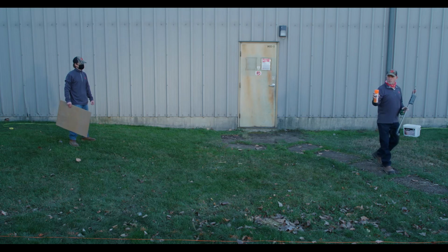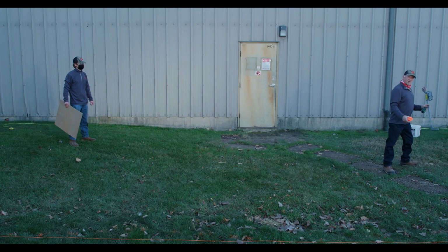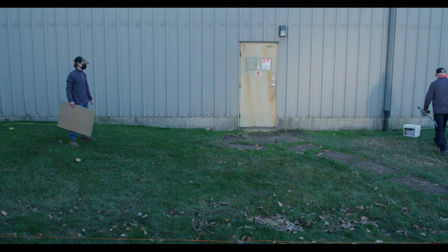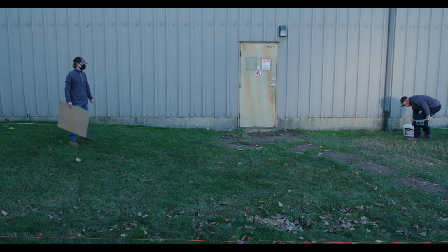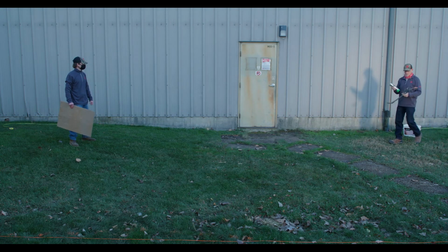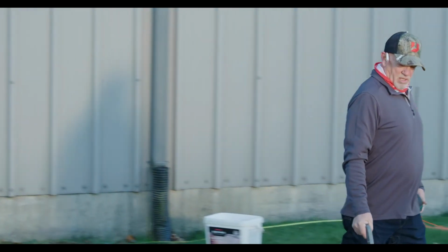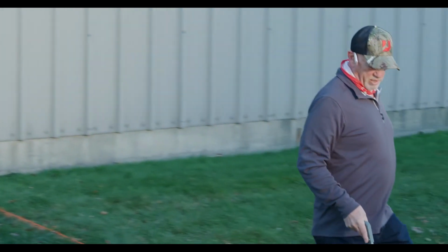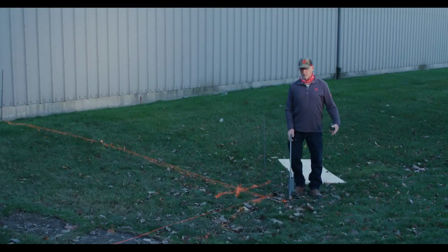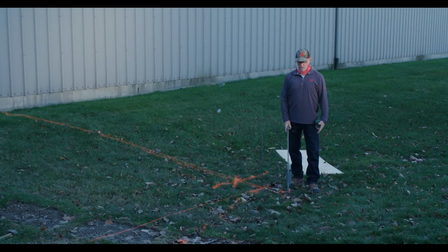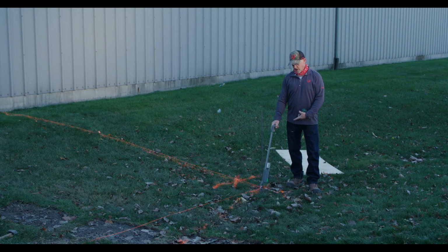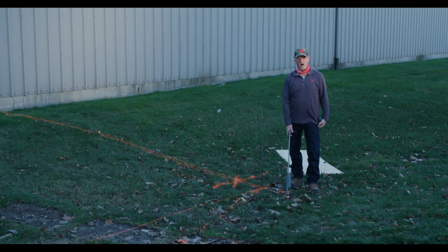I'll stand upwind, clean that tip. Switch colors and then begin to spray paint 1 foot beyond my orange marks. So again, similar to that drawing that you saw where the dashed line was to the outside, this is really the hard line that I like to paint because this is where the shovel hits the ground.